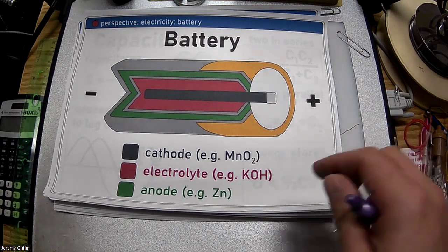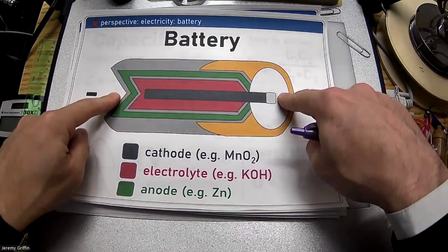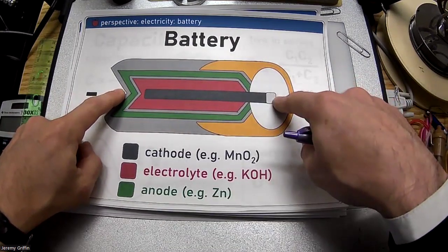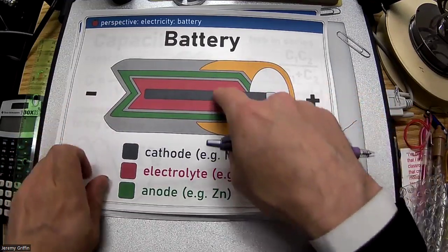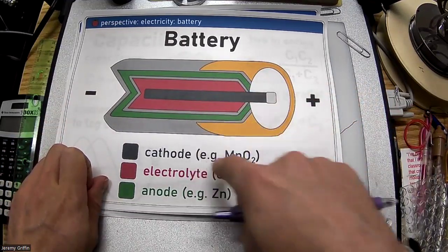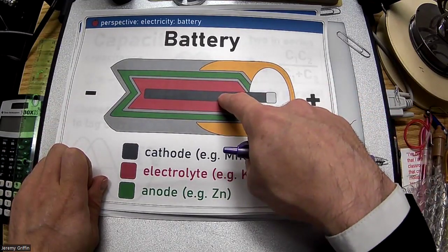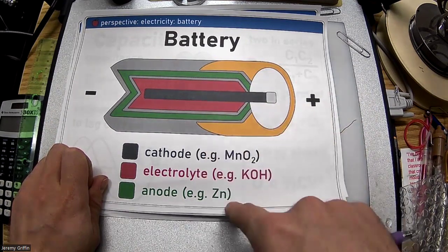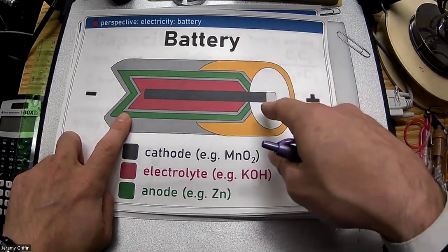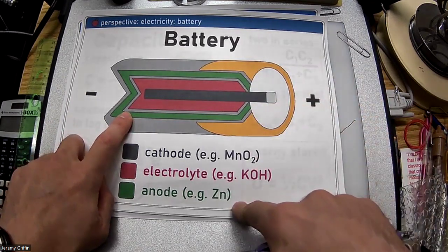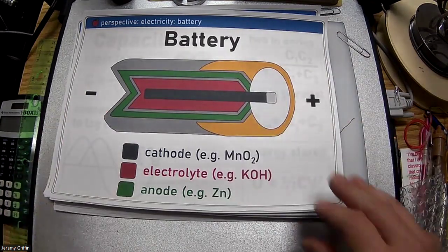Right, now, if you just leave that sitting on the shelf, then ideally there's nothing going on. It could just have a shelf life of like many years. Right? But if you can somehow get this positive and negative connected, and ideally going through a resistor, right? So then short out, right? Then now that potential difference is going to drive a current, and there's a chemical reaction that happens inside the battery. Right? So ultimately, what happens is that there's an oxygen that leaks over into the zinc, and this becomes zinc oxide. And if you run the course of the life of the battery, then at the end you'll have a bunch of zinc oxide, things like dimanganese trioxide, I think is what it is, right? And that would be an expended battery.